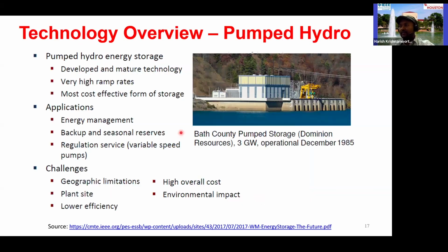Now, just a quick heads up on the pumped hydro. As I mentioned, you have two levels, water at a higher level as well as a lower level. When you have excess energy, you can pump the water to a higher level, and vice versa. But some of the challenges are that it's very high cost, and you have several geographic limitations. We probably won't be able to use that everywhere. So that is something that restricts the use of pumped hydro.